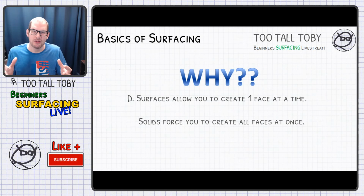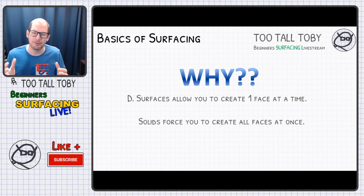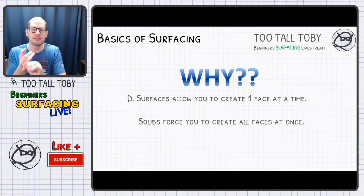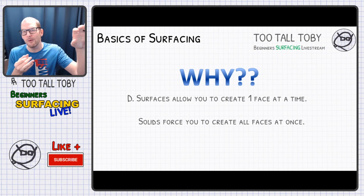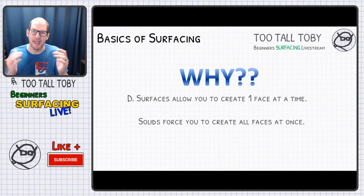Now, why work with surfaces? Surfaces allow you to create one face at a time. Solids force you to create all faces at once. So we've seen a couple examples of why work with surfaces so far. Like we saw how you could use a surface as a plane. That might be a spot to use surfaces. I wouldn't really consider that surface modeling, but it is a cool tool that you can use. You could use surfaces to fill a single face of a model that imported that had a problem. You could use a surface for that.